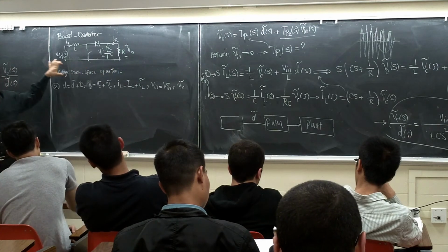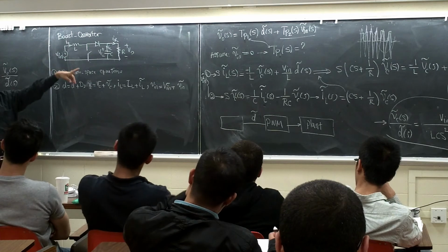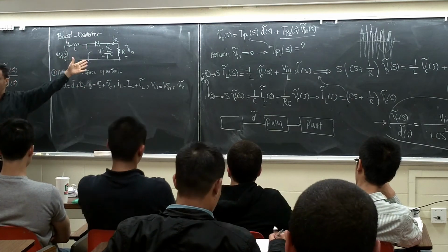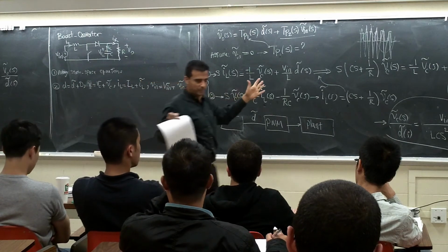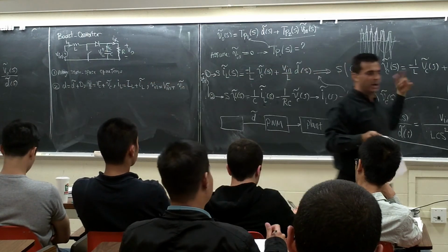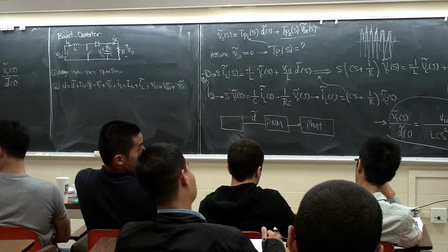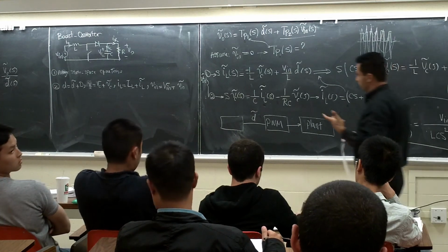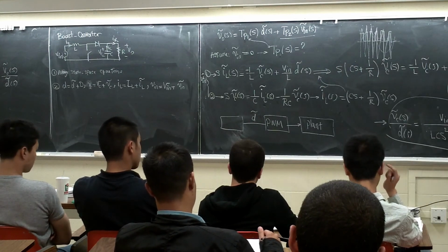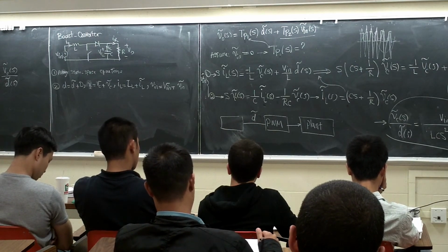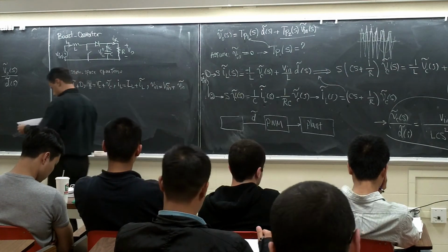Go to the notes you have, right? Just go to that equation directly. You don't have to do it the way I did it here. The final equation I found for you, for the buck and for the boost. I found it for both of them. Go to the equation and replace IL, VC, D, and V in with these values. Do the calculation, the multiplication, all those kinds of things. You're going to get to this equation. This is what you're going to have.